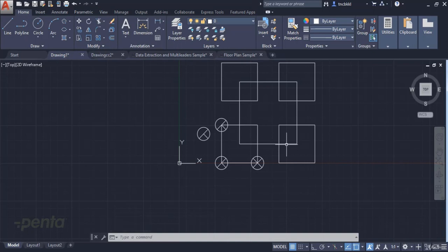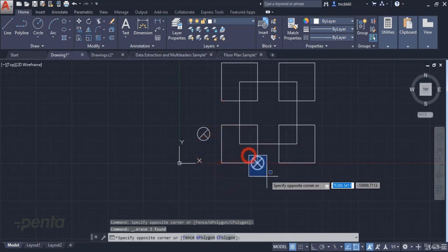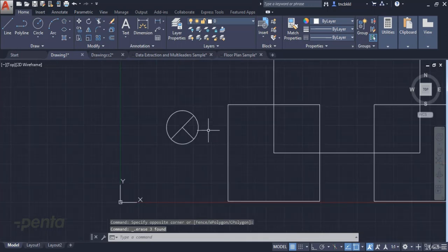This is just like you're using a bolt in a project with a length of 50 millimeters, but you want to convert it into a standard 55 millimeters. If there are 1000 bolts in the project, then you would have to convert it into a standard 55 millimeters manually. Here, we can solve these problems with the block method. It's faster to use and manage. So, how do I turn this object into a block?